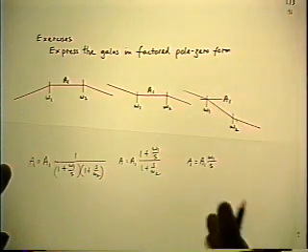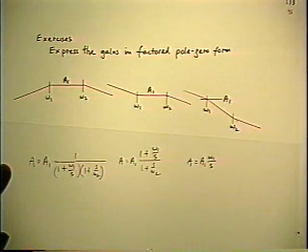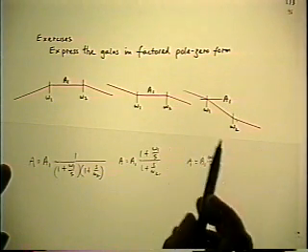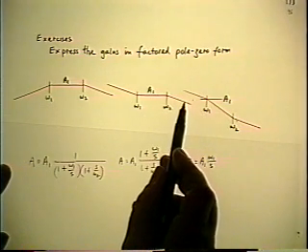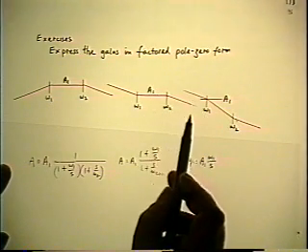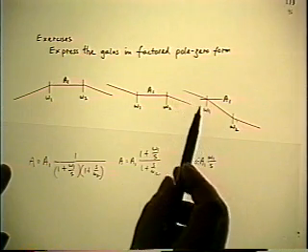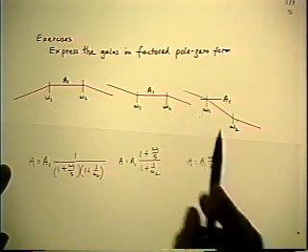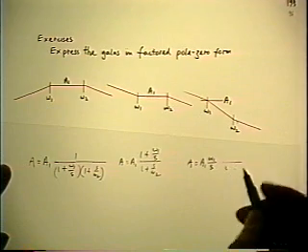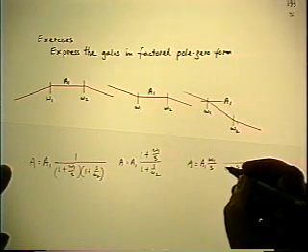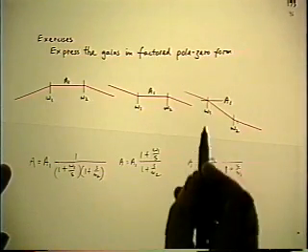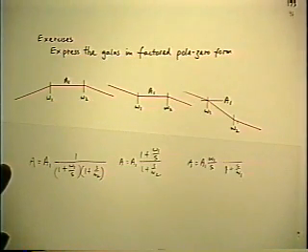And from there, it's nothing new. Because now we've identified the left-hand asymptote, and all you do is look up in frequency. Nothing happens going down. If you look up in frequency, you see a normal pole at omega 1. It just happens to be the same frequency we already used as reference.